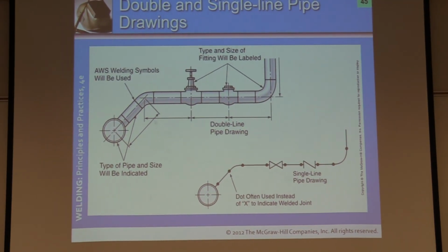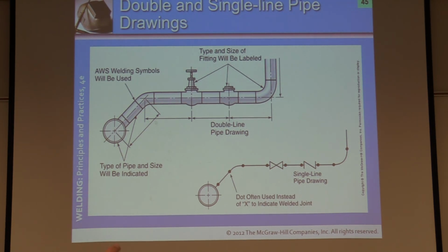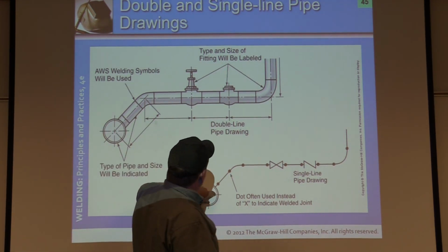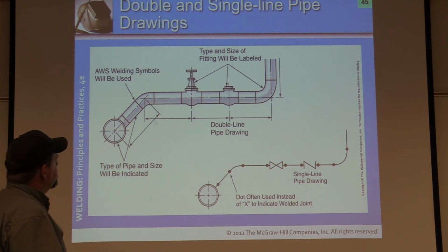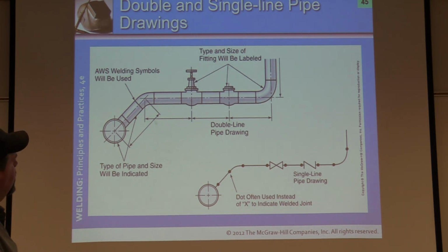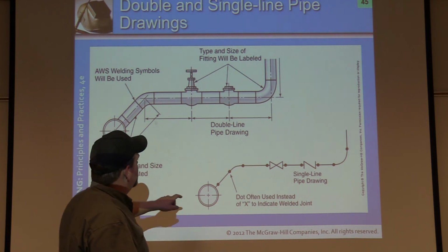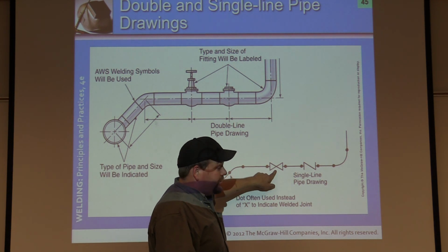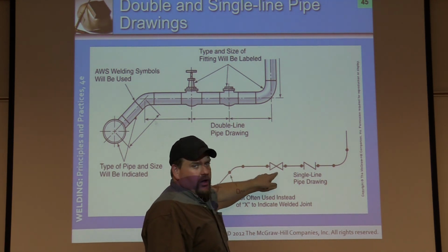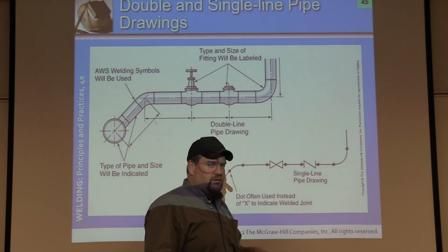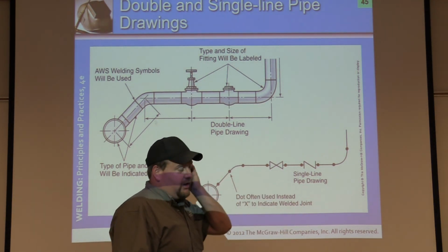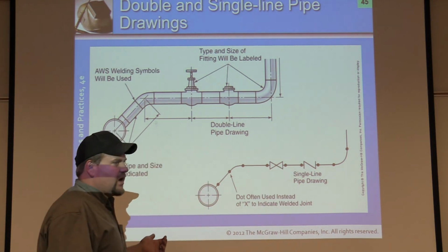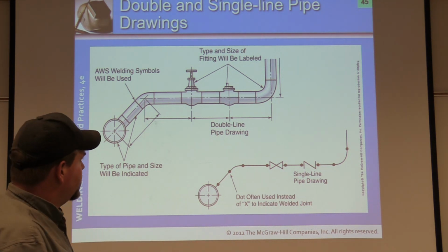So in this case, what we're doing is just showing a print. This is a real life drawing, what it should be. Here's going to be your single line pipe drawing. This is typically how you will see it. And then this might be denoted, in a larger print, as valve 1. Then you'll go to the note or the material supply and detailed section, and it might say valve 1 is a 2-inch, 160-pound gate valve, not a ball valve, with extra information and so forth.